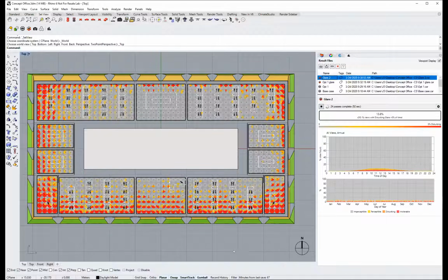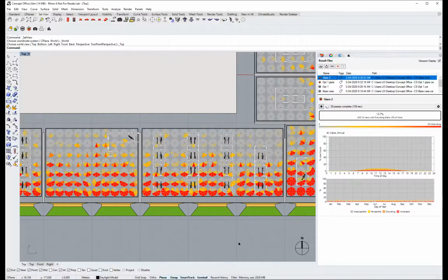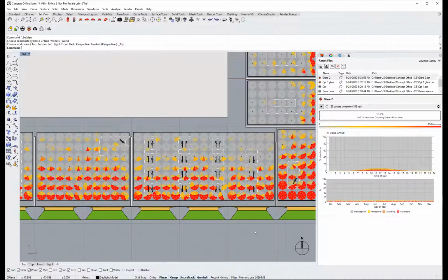And now this is where having these view directions becomes very useful, because you can start to tell a story about interior layouts too. So we talked about imagining this as a concept design project where we're doing the facade, maybe the layouts aren't totally fixed. One thing that both of these maps indicate is that the worst glare problems happen, perhaps unsurprisingly, when you're looking directly out of the facade.